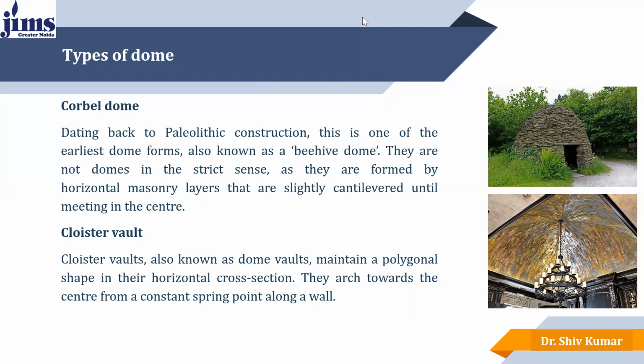Now the next is the cluster vault. Cluster vaults, also known as dome vaults, maintain a polygonal shape in their horizontal cross section. They rise towards the center from a constant springing joint along the wall. Here we can see in the images the first one is the corbel dome, which is constructed from stone, and here we can see the cluster vault, which is shown in the second image.